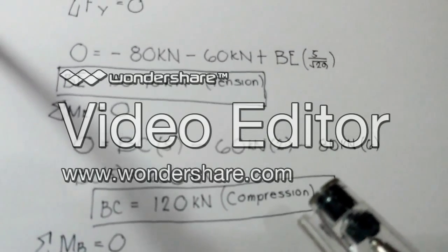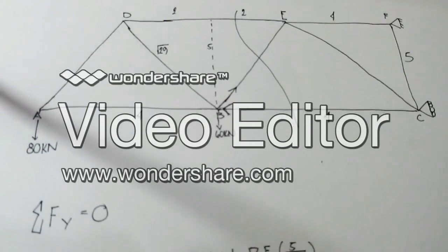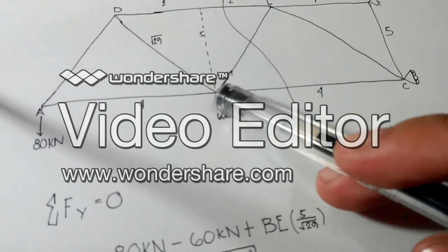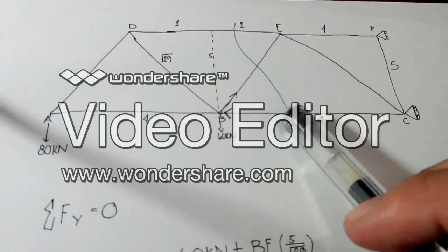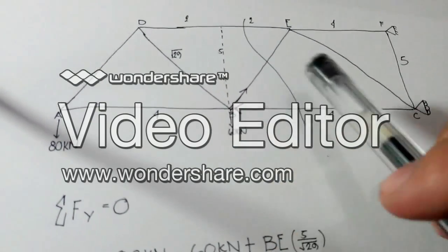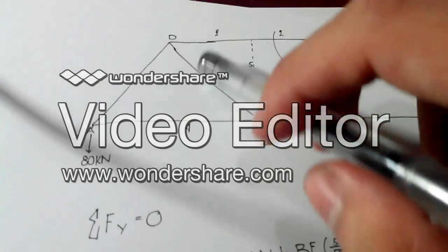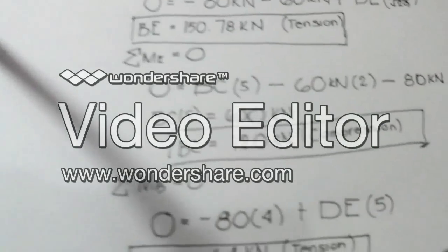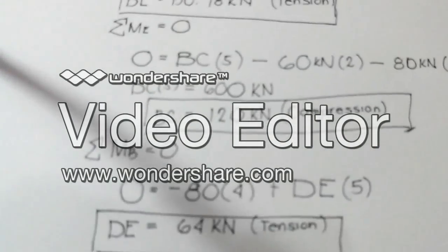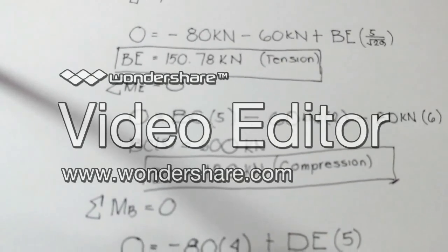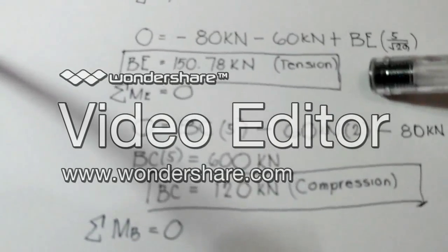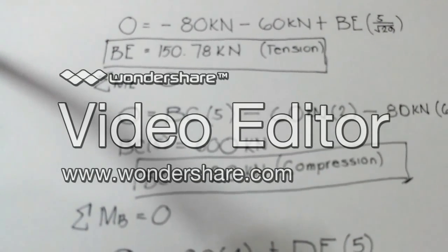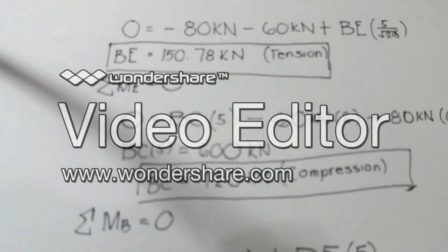And since it's positive, meaning it rotates the truss clockwise, here's the force B. It's going towards B, so it's clockwise and it's positive, so it's compression. Now we have obtained BE and BC. The only internal force we need to determine is DE.